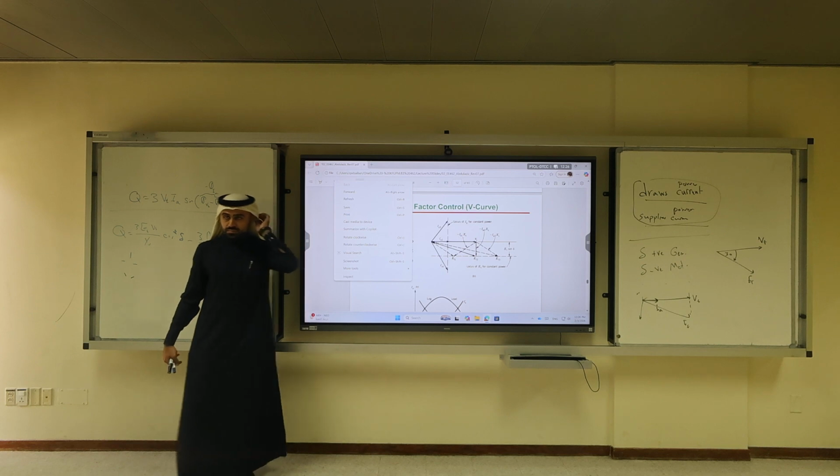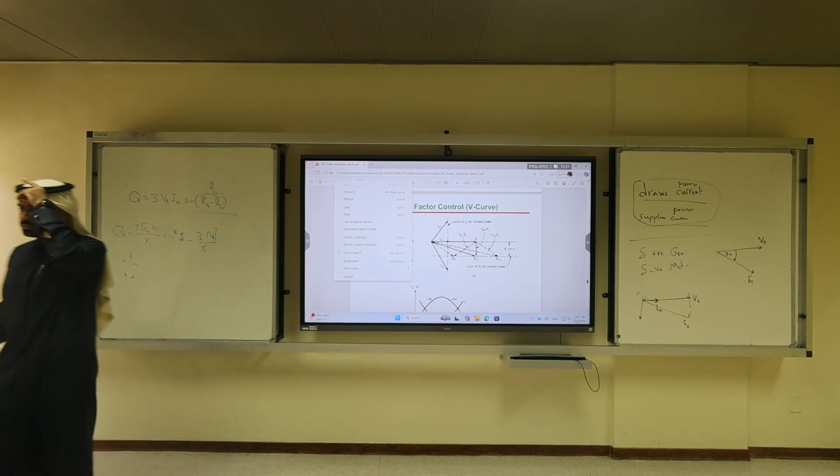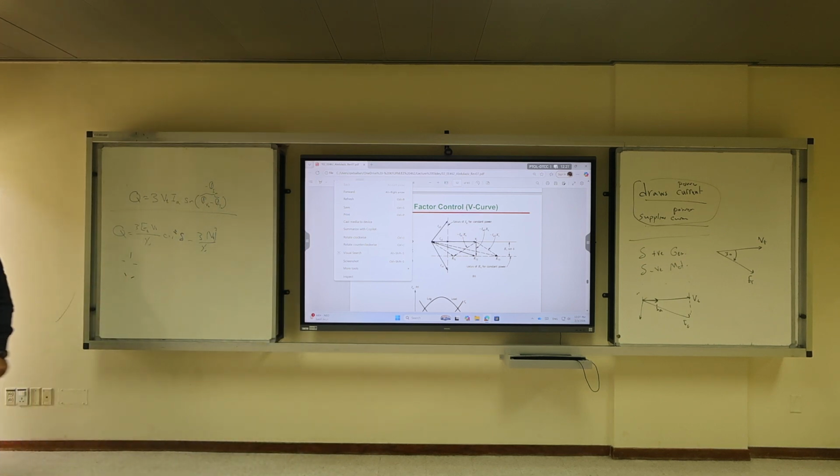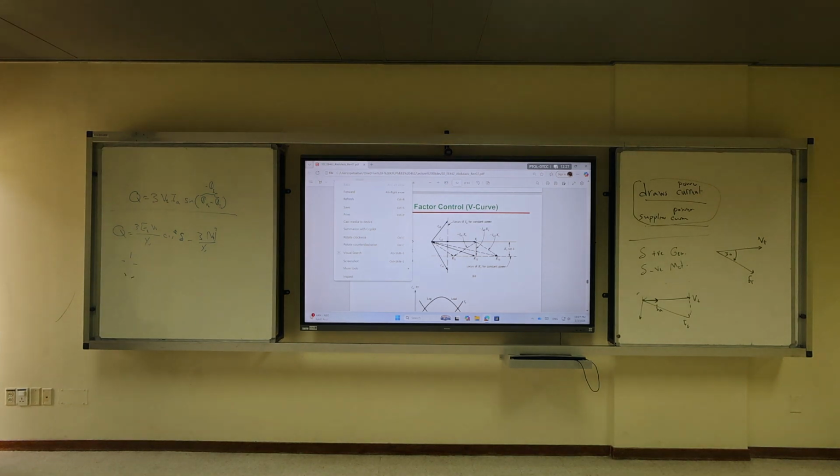So, Doctor, when choosing a motor, we should aim for higher torque than the one we will be driving on, right? Not really. It's a function of the gearbox that you're using. The shaft is not directly connected to the tires. There is a gearbox.